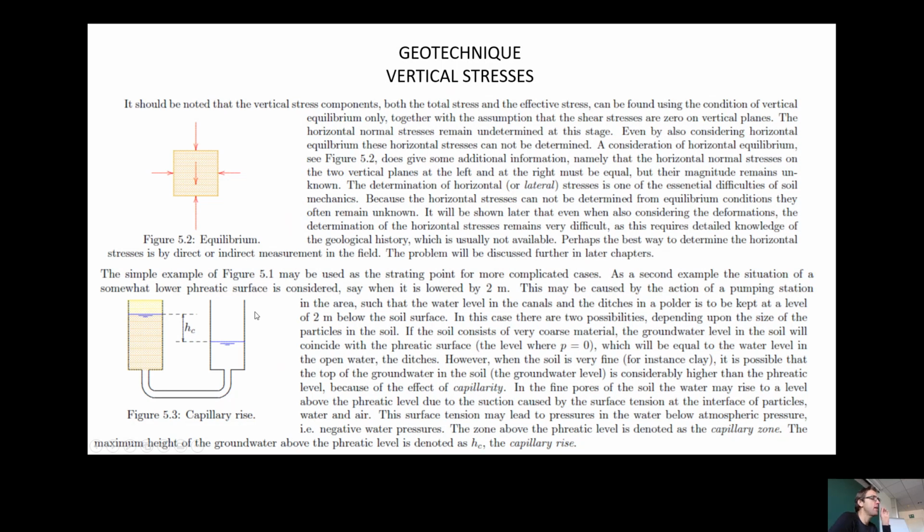For now, we can consider this figure, where you can see what we call a capillary rise. In this case, we have a movement of the water from the soil into the container without the soil, and this movement is what we call capillary rise. I don't want to enter into more detail because this is what happens generally when we study the drain. Again, the zone that is above the phreatic level is considered the capillary zone.